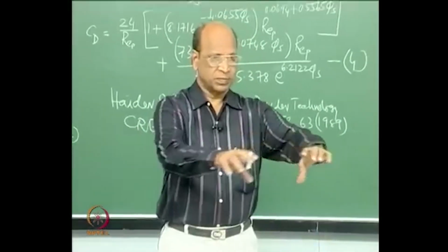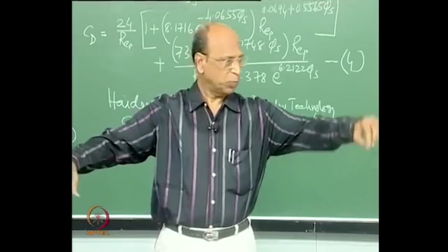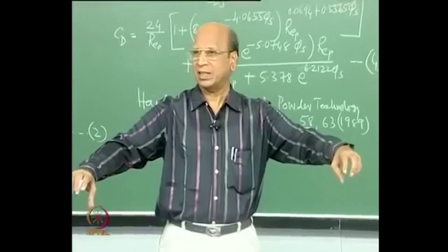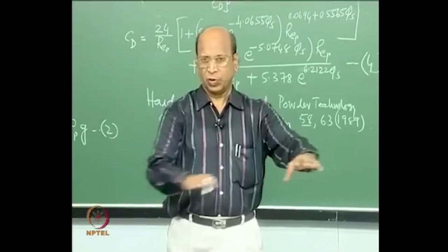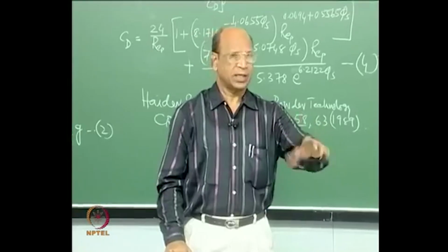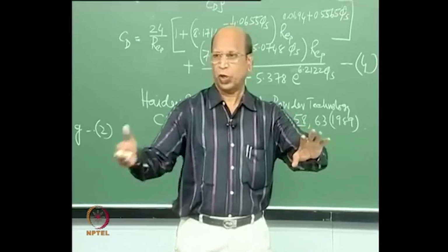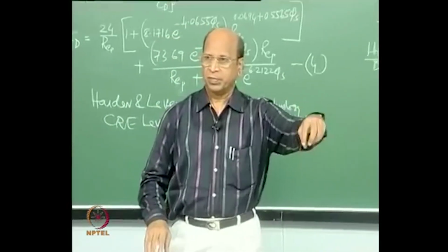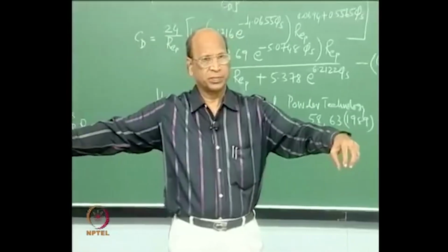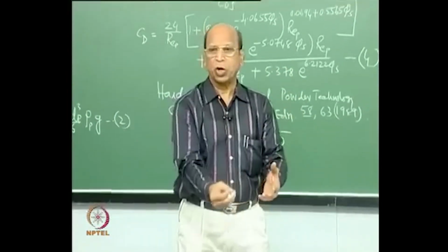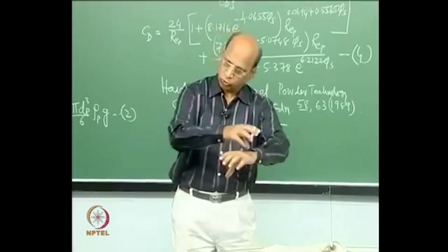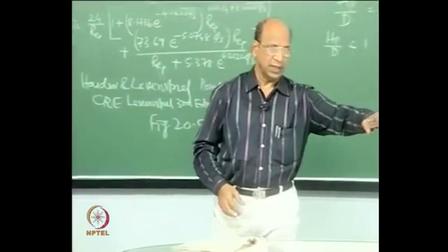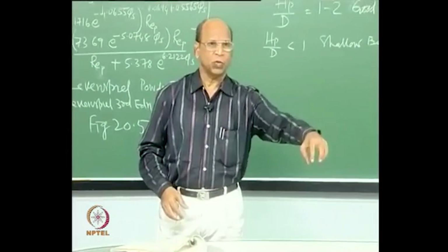You increase the length, and then put the solids here. This is just a plate with perforations, maybe with a slight angle for flow. Even if you do not need a slight angle, it is better to have if you want better flow. Otherwise, even if you put it horizontally, you are feeding here all the time, and it may be 2 meters length, a straight channel, and at the bottom you have the perforated plate, and you uniformly distribute the hot air throughout the channel, and the wet solids are put in one corner.